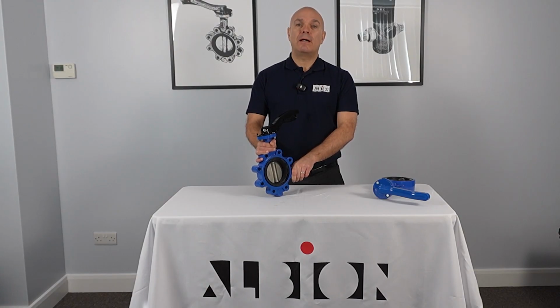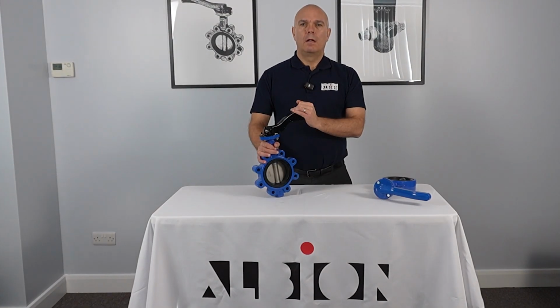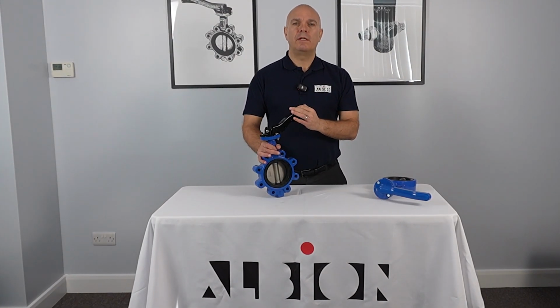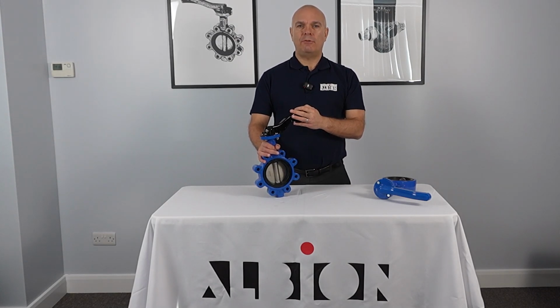There is a reason why wafer type design and lugged and tapped type design have different connection characteristics, and this is because it allows a lugged and tapped type design to be used for end-of-line service applications, as it can be securely fastened to the flange by way of bolt from one side only. The most important thing to consider when using a butterfly valve for end-of-line service is that the maximum working pressure should be reduced by 50%. At any other time, it is good to operate at its design rated pressure.